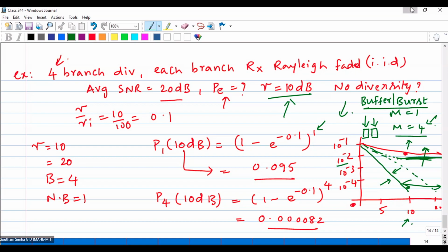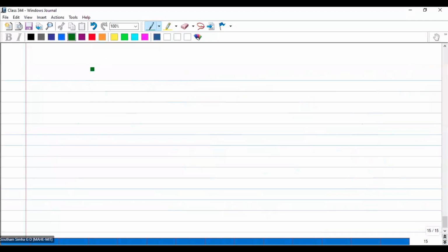Now, this is a very interesting question actually. It's very difficult to answer, but I have a solution because in your software defined radios, first you have to estimate the channel. When you estimate the channel, you will get the probability mass function, or your CDF. Once you get the CDF, you will get the PDF. Based on the estimated CDF, you will curve fit it back and assume a distribution which is nearly equal. Now I'll show you once again. I think my screen is visible. That is why the Chernoff bound and union bounds are available for this.